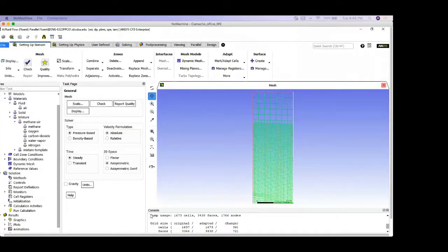Now, because we're trying to run a combustion simulation, we need to ignite the flame. So we have the inlet fuel air mixture coming in. We also need to ignite it. So we initialize conditions for that. It's not boundary conditions, but initial conditions within this region, to tell it what the profiles look like.